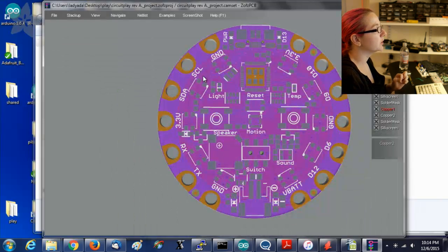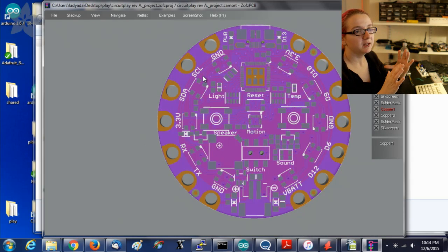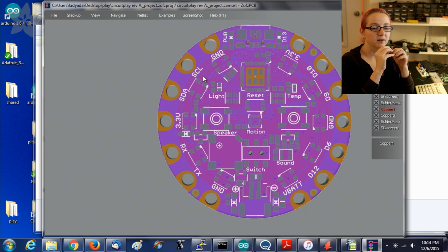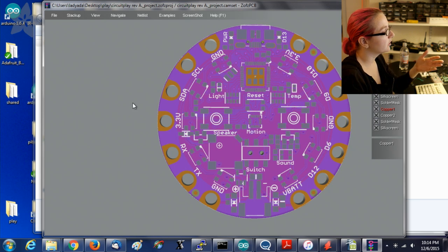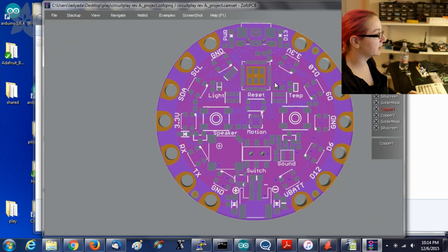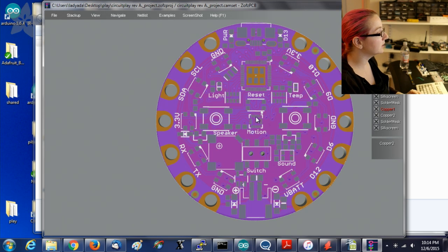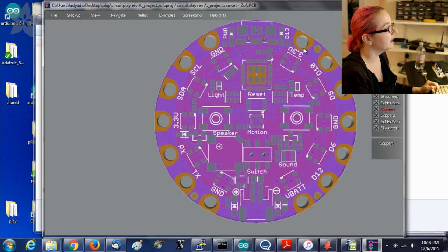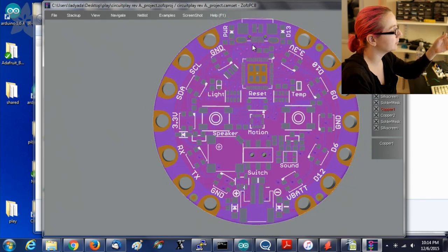But when you're looking at the volume of it, sometimes the green vias seem like they're elements on the circuit board that are exposed, but they're actually tinted. So this shows you, look, the vias are tinted. You actually have quite a bit of silkscreen space available here and here and here and here. And down here, I could probably even fit another component or two if I wanted to. But anyway, what I wanted to show is, and you can turn off the paste if you want to see.